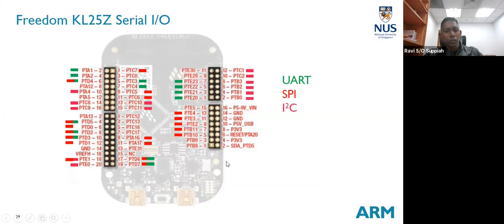When you are doing the PWM and the UART, and then you look at the other requirements of your LED and so on, you now need to make some design choices: which UART do I use, which PWM do I use, and which pins are then available for GPIO functionality for the LEDs and so on. So you need to come up with a plan to separate out all these different requirements and see what the mapping is.